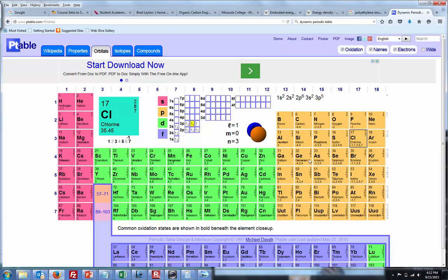One thing, it says gallium arsenide cells have a band gap wider than silicon. It says one's close to the theoretical optimum for absorbing the energy in the terrestrial solar spectrum. So it's more or less tuned to what's coming out of the sun. So cells made from gallium arsenide are therefore more efficient than monocrystalline silicon. It also makes them more applicable for concentrating arrays.